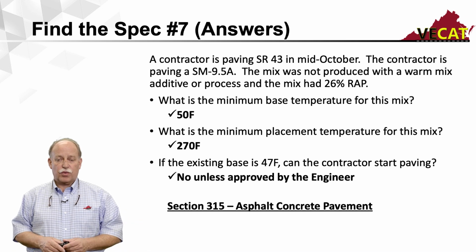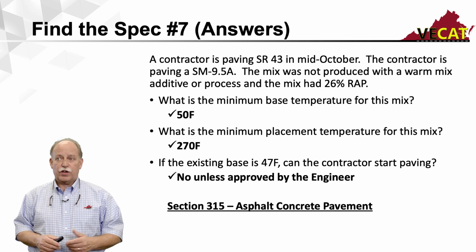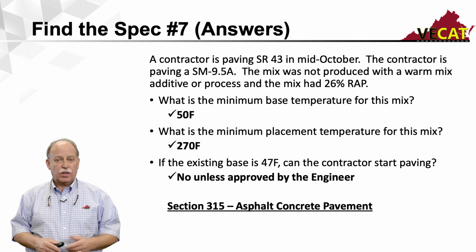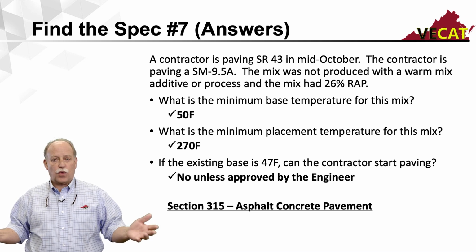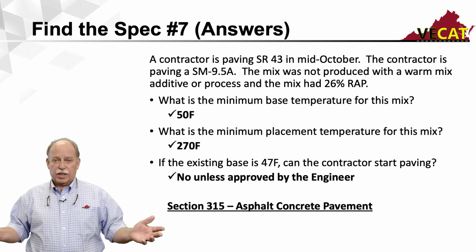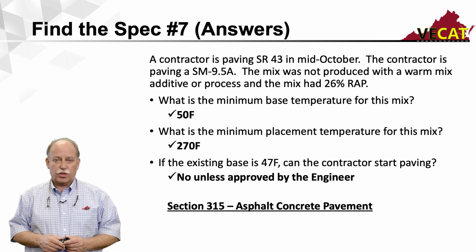And those are found in your Road and Bridge section 315 for asphalt concrete pavement. And you will see that the minimum base temperature for that mix is 50 degrees. Some people say, well, wait a minute, I look in there and I can see that it says 40 degrees. Well, keep in mind, you have to look at the spec closely, because in this case, it's critical to note